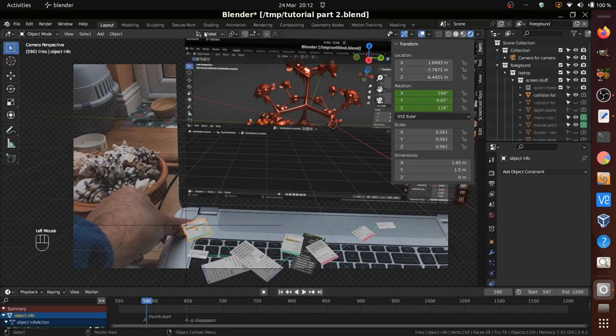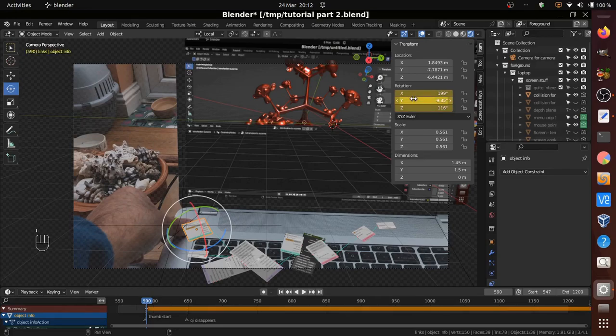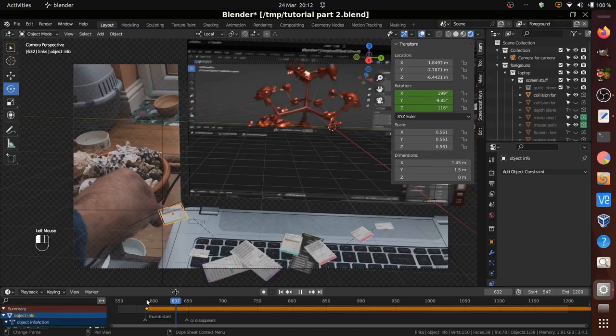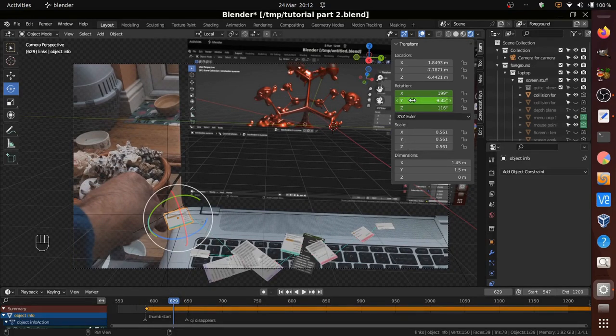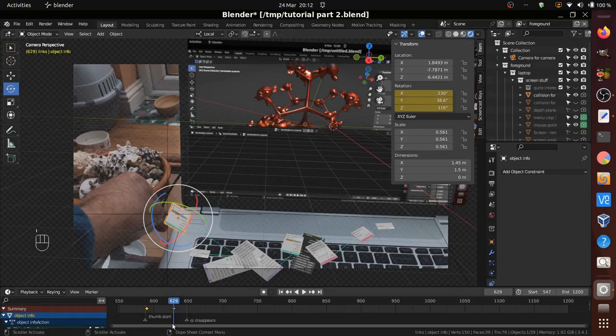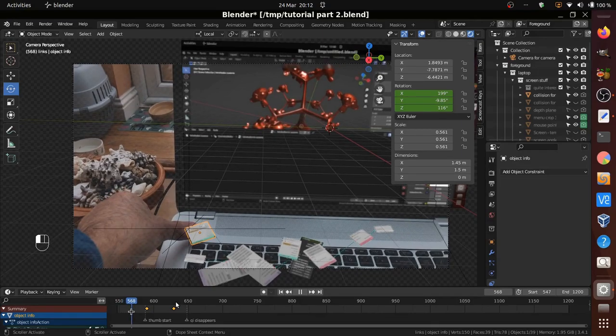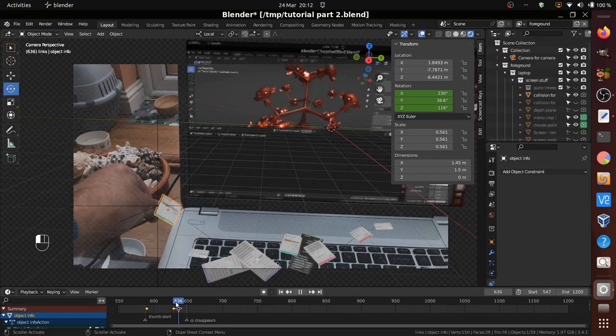In order to get the rotation of the front plane node, it is easier to use the local transform orientation and the rotate object cursor to alter the X, Y and Z angles in the sidebar panel. And keyframe them. When I tried altering them in the 3D viewport, all kinds of weird rotation animation happened.